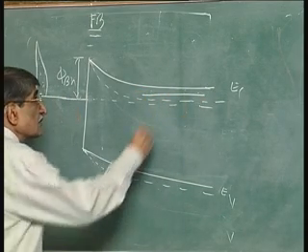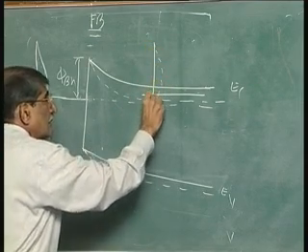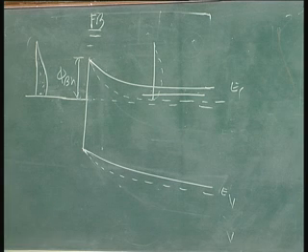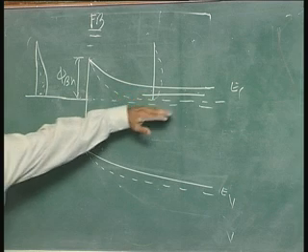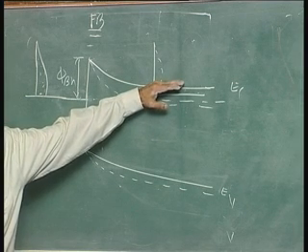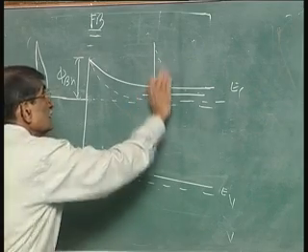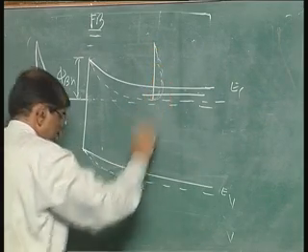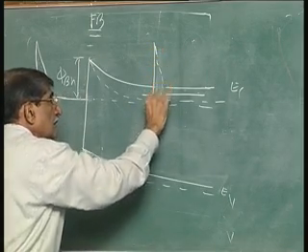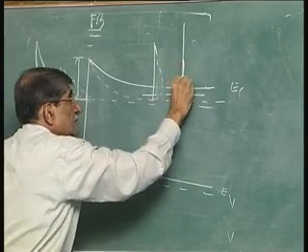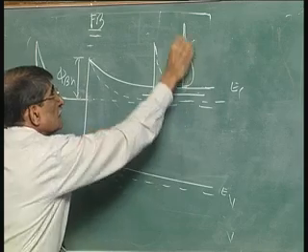What happens to the energy distribution? Originally it was like that. Please understand, the dotted line was originally there, I do not want you to see it now. So, when you apply forward bias V, the whole thing will get shifted by an amount equal to V. So, the barrier will reduce by an amount V, forward bias. What will happen to this distribution? What was like that, this distribution, will become like this now. Same thing, but it has gone up.